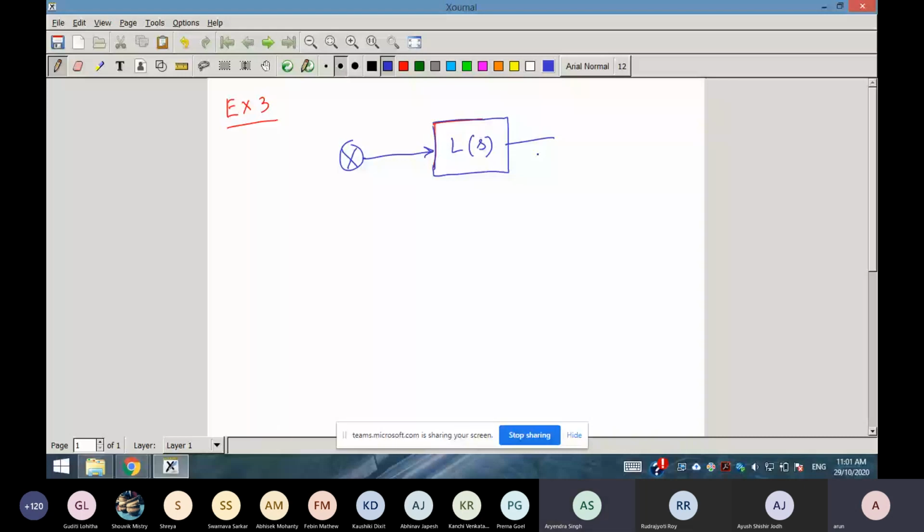Okay. LS is... so gain margin, phase margin, all these things, root locus, all these things are drawn for the loop transfer function. Okay, so loop transfer function is plant transfer function into controller transfer function. Got it?